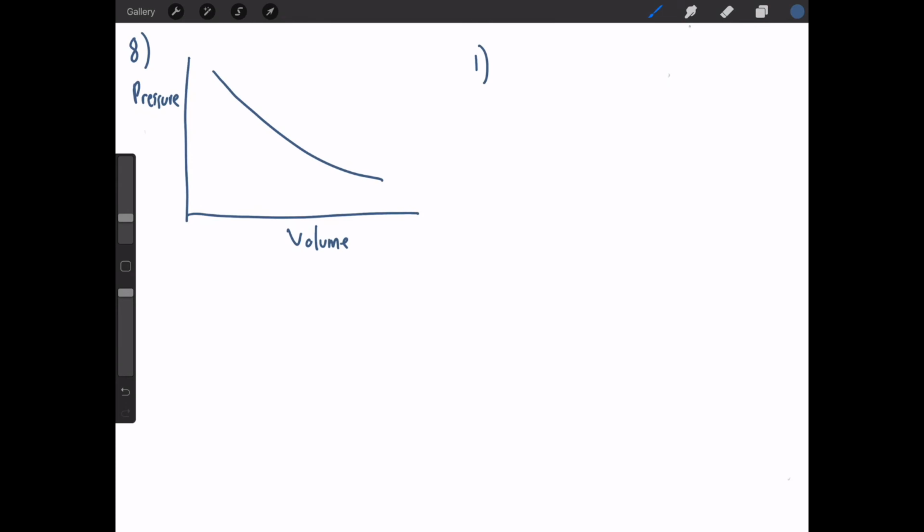What does resolution mean? Well, it's the smallest increment that a measuring instrument can measure. So looking at this, the scale is quite clearly 1 centimetre cubed. A lot of people put 25, that would be the range of this. That's the total difference between the smallest and the largest measurement. Resolution is the smallest difference it can measure. Easy mark. Don't lose marks on that one.